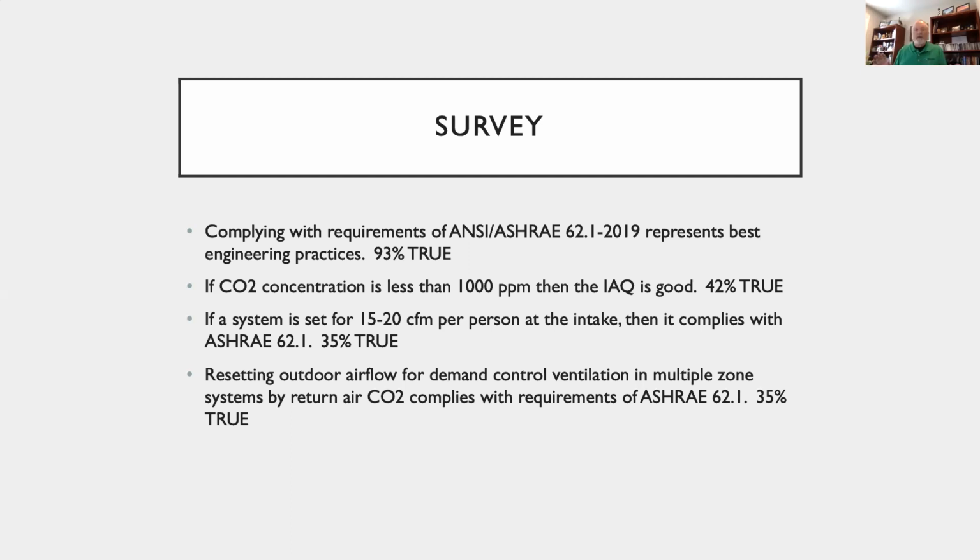Look, I've dealt with indoor air quality for more than 30 years. I don't know the answer to that. It's generally not just CO2. You can go almost any place in the morning and measure CO2 less than 1,000, and it may be horrible. It doesn't tell you whether there's bacteria in the air. It doesn't tell you whether there's mold. It doesn't tell you whether there's harmful chemicals. It doesn't even tell you if there's carbon monoxide. It's only some rough indicator of how many people have been in the building for how long. So it's not really a good metric in terms of whether the IEQ is good or bad, because there are so many different things in the indoor air.